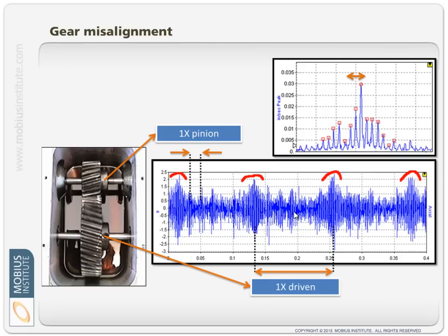Now, the spectrum might show us this. These are sidebands in the spectrum. We didn't really explain that, but that's just one of the complications of, well, I shouldn't say it's a complication, it's actually very helpful, but we see all these little peaks, they're called sidebands. It means there's modulation. So if we do our spectrum analysis properly with enough resolution, we can see this. But we can see this for a lot of different reasons.